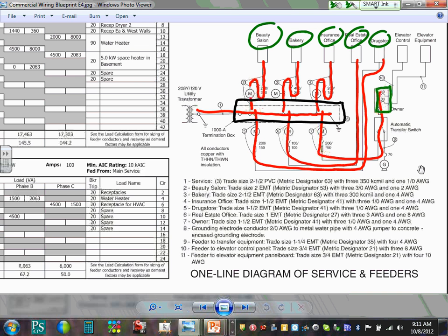Okay. So we brought a service, 208/120. Can everybody understand the meters? We have a meter for each one of them, because each tenant is going to be paying separately for this service. We have meters, and after the meter, I want everybody to understand where we have a disconnect. Can you guys see the disconnect here? The fuse disconnect for each one of the tenants. Why? This is your service entrance disconnect means. Service entrance disconnect means. With a fuse, of course, you have to have a fuse.